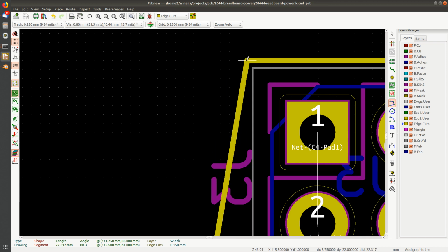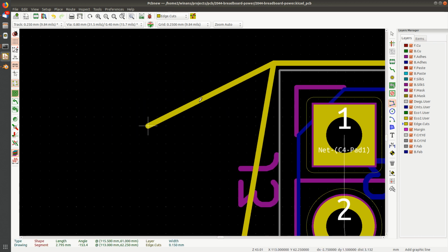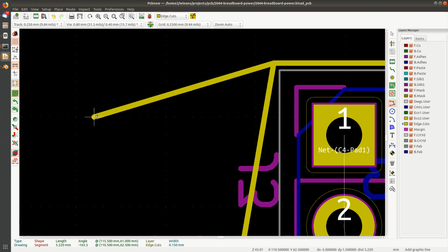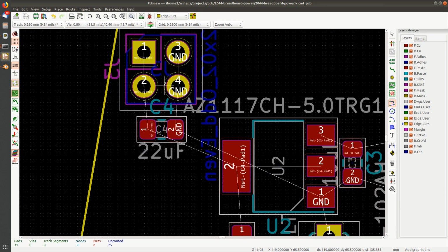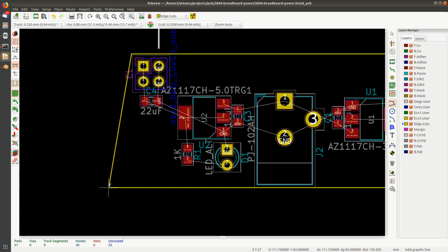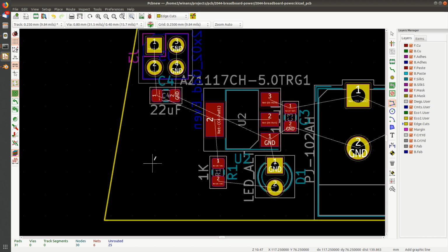You don't really know exactly where it's supposed to be. You know where it's going to end. It's going to end right there. And I'm still hitting the left mouse button. And now it won't go away. If I hit escape right now, what will happen is the very last segment will disappear, and I'm left with the guys that I drew with the 4 clicks. Now, the problem is, this point I didn't really know where to put it, but now I do. I want it to line up with this dot up here.